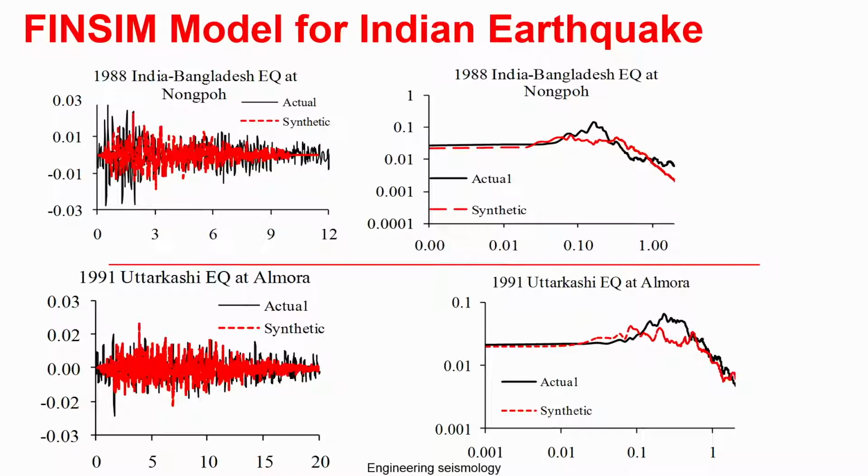As I told you, the source parameters and path parameters all contribute to that. We even made some parametric studies to fix the source parameters of a particular earthquake when they are not available. That means we alter the parameters and try to match 2-3 records of the same earthquake exactly. Once it matches well, the same parameters are used to simulate at different distances and magnitudes for the same source. That was the process we took up.